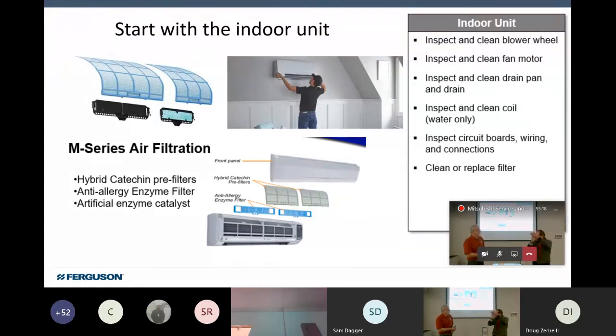The air coming across that coil is then going to possibly blow that off. It has to do with a partially wet coil and a partially dry coil: right where those two meet, you've got higher velocity air going across the dry section. It'll carry the water right away, and that carries to every coil basically. Yes. Something to be careful about.